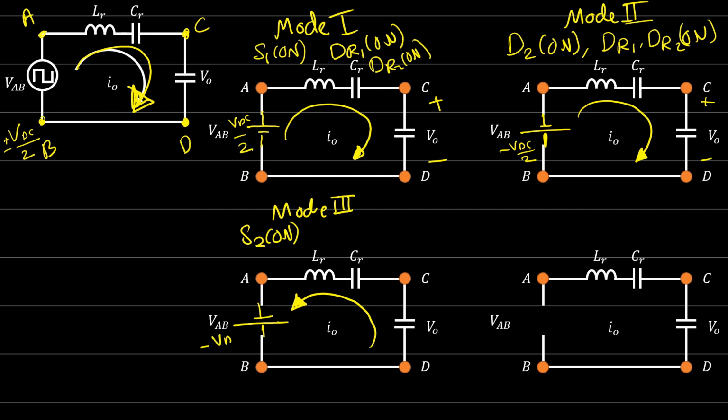And this is minus VDC over 2. The output is negative as well, so this is the other option. So at this moment, diode 3 and diode 4 are conducting. Now what else we have? When the input is positive, output negative, and the current is negative. So this is mode number 4.